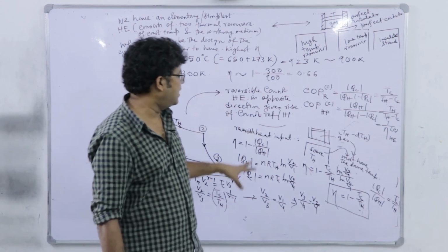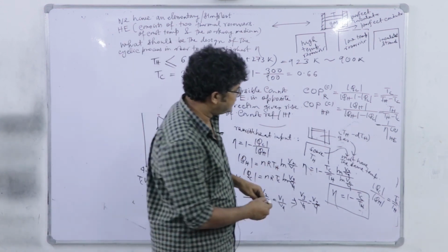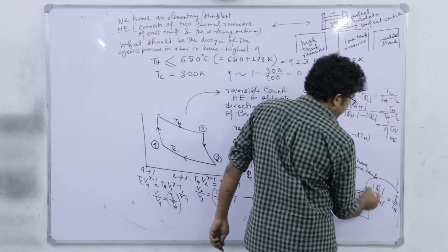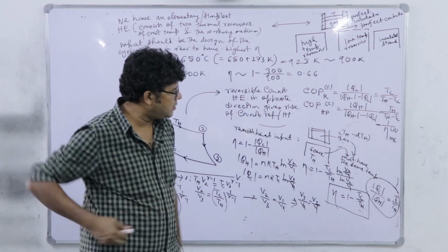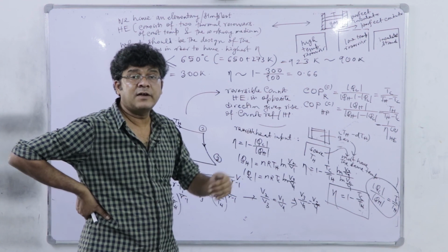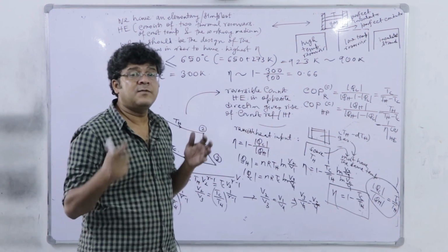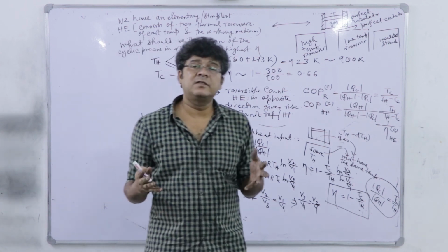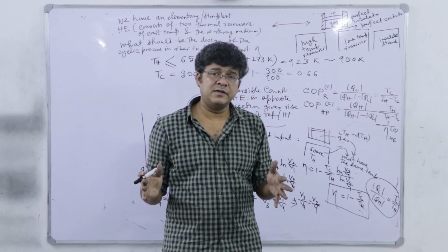And with this idea of Carnot cycle efficiency, and specifically this equation mod QC by mod QH equal to TC by TH for a Carnot cycle, in the next session we will try to generalize this concept to any reversible cycle, definitely with multiple reservoirs or programmed temperature reservoirs.